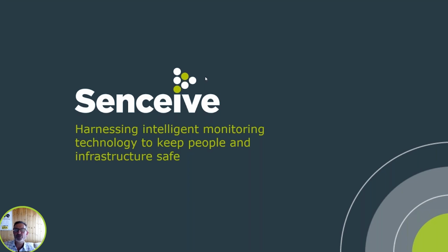The first backup is that the gateway will store data, typically up to 30 days. So if it's not able to export its data directly from the gateway because of a failure of the cellular network, then you have the option of manually going to site and downloading, or it being transmitted when the system is back up. And in most situations, that is the effective route.